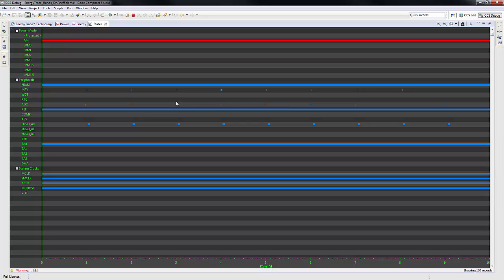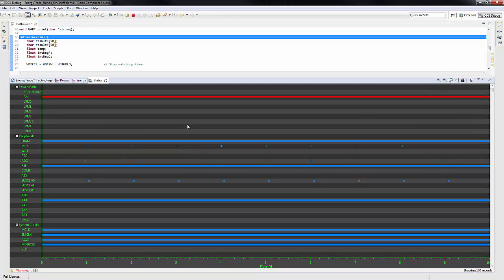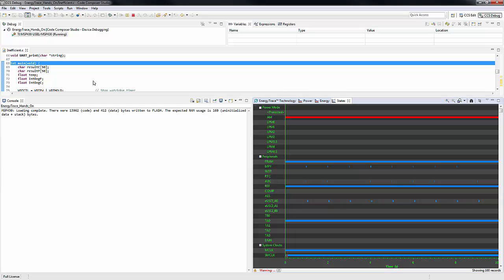So by it not being displayed here, it does not mean that the ADC did not run. Of course, if you use an MSP430, which has a higher resolution sample rate, you will see all of this. If you see in the slides, number 28, the MSP430 is actually capable of measuring and capturing at 4 kHz, so you see all of the state transitions perfectly.